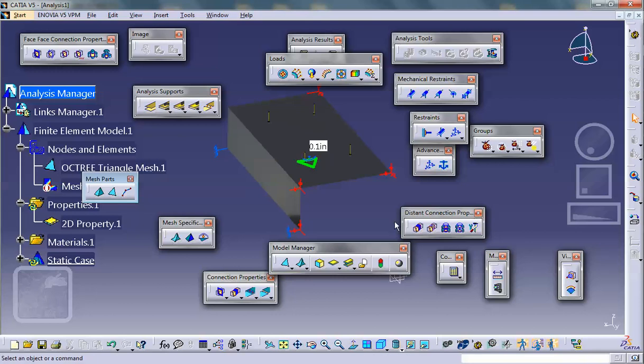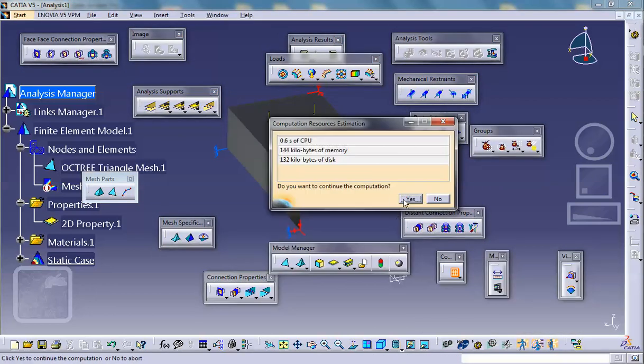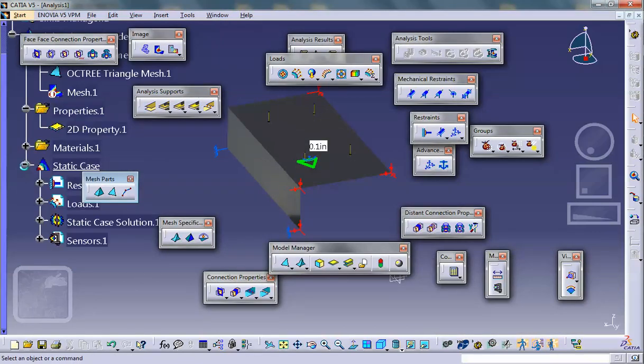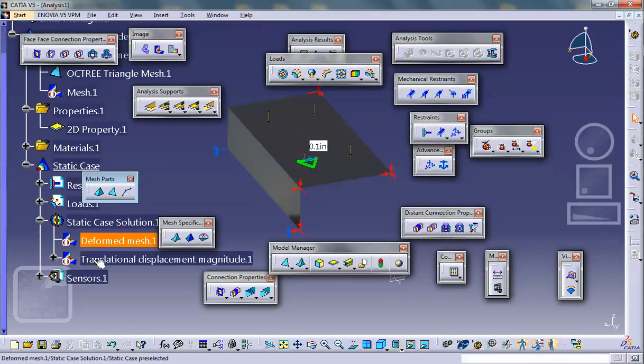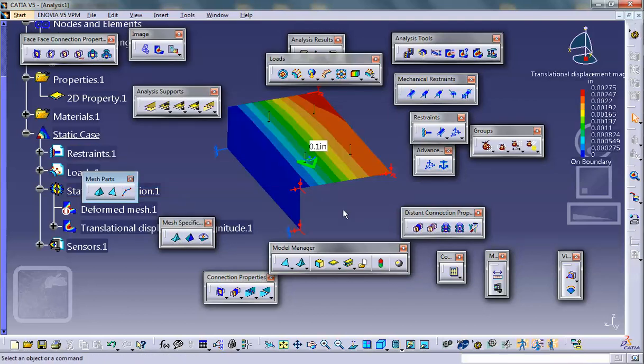And now look at the deflection one more time to see if it's meaningful. And now you can see it's a lot better. You can see that the maximum deflection is 0.00275 inches. Deflections are important. However, you should also look at the stresses because deflection may not give you a good idea,